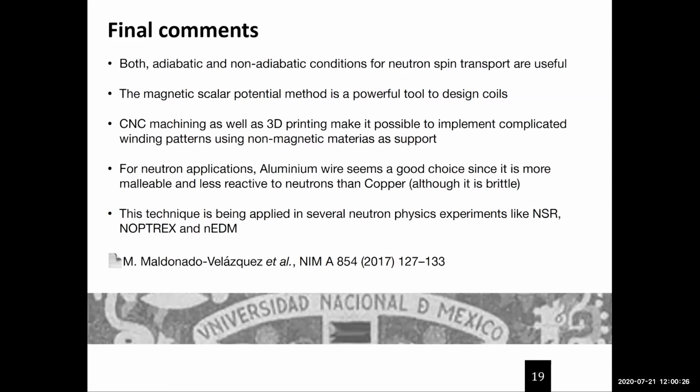Yes, that's painful, or then you need to be very careful when you are assigning current to each of the contours to assign the current in the right direction. What we do is we have two different currents, one positive and one negative, and since the contours are in different directions, we need to check one by one that we have the appropriate current. So yeah, that's a complication.